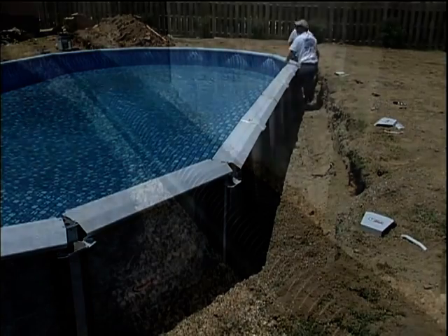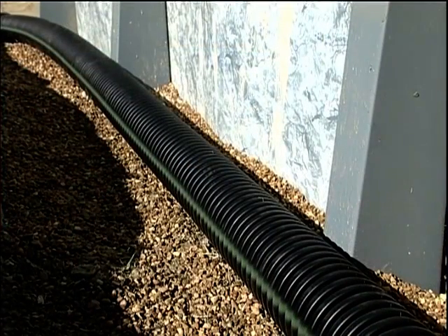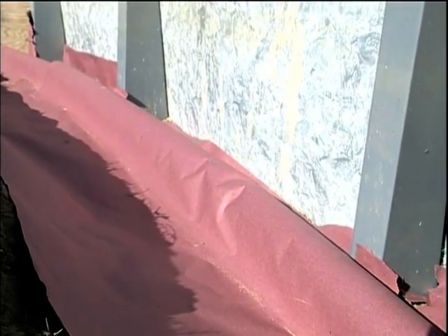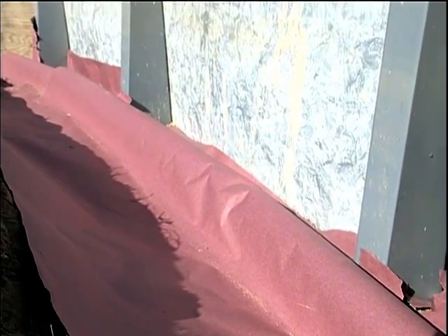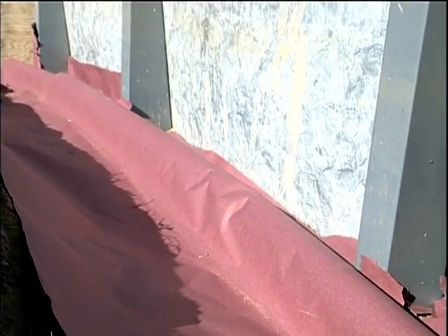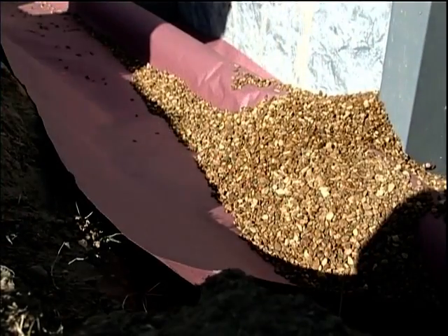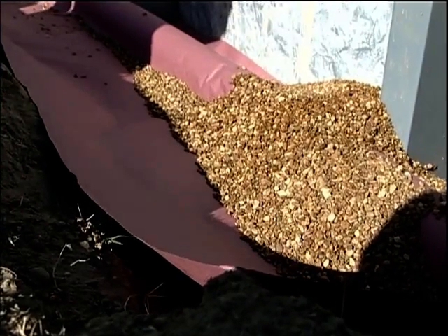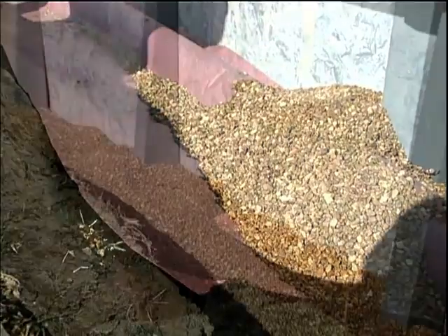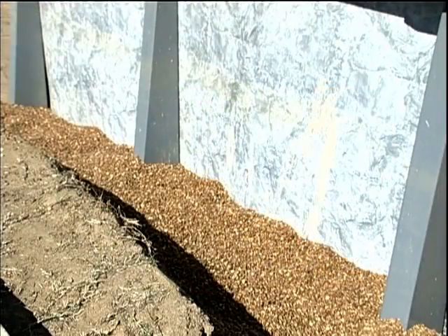To begin drain installation, create a base of about 2 inches of gravel. Then set into the gravel the drainage pipe. The pipe should be covered with a paper or cloth designed to allow water through, but keep the soil from clogging the pipe. After setting the pipe and drainage paper into the gravel, then cover the pipe with gravel. At this point, it's time to start to mix the slurry.